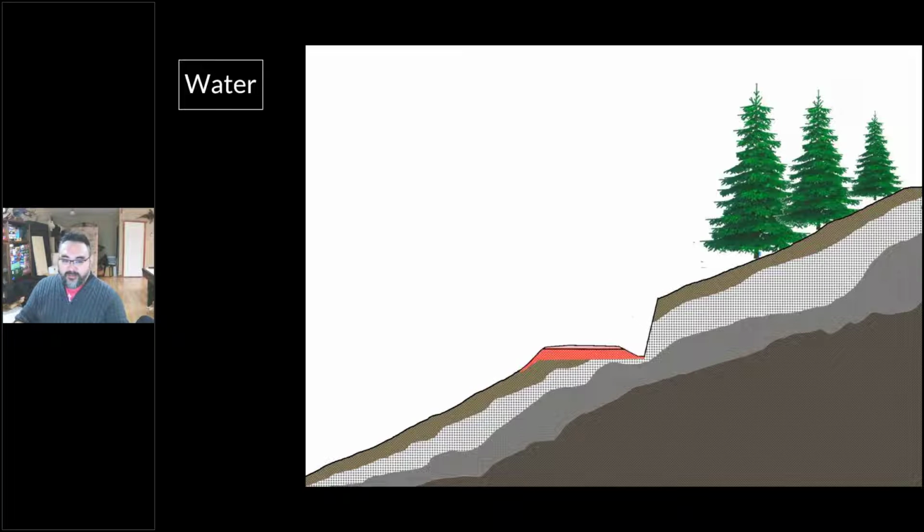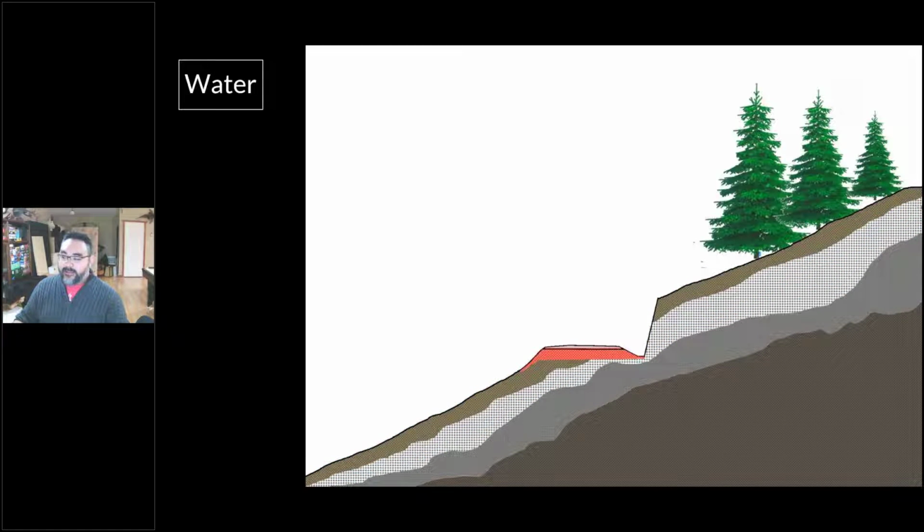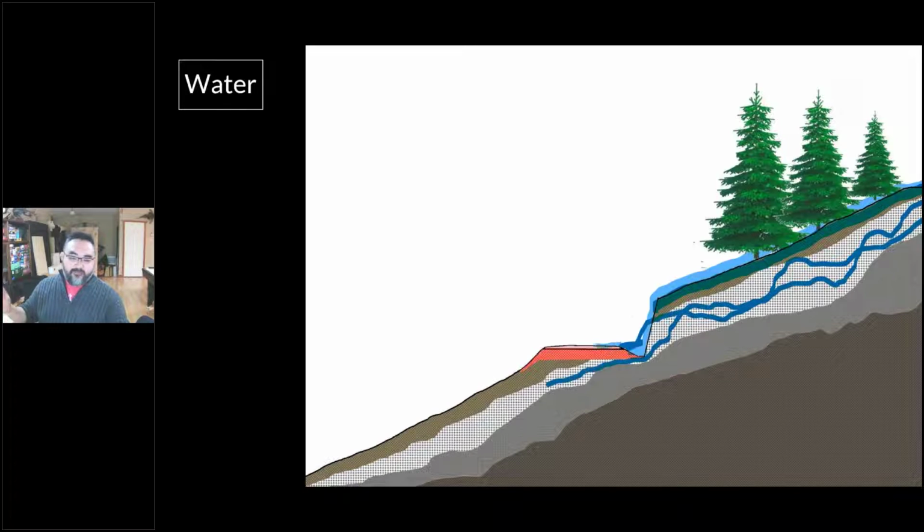There will always be an impact on water when you build a road. So as we cut through that soil profile, you can see the water is going to be coming down the surface. Even the surface water speed, as it comes off of the forest floor onto a cut slope, is changing its velocity. It's even more dramatic for that subsurface flow that we're catching that's emerging from the cut slope, flowing down it, and either concentrating in the ditch or flowing over the road and down.